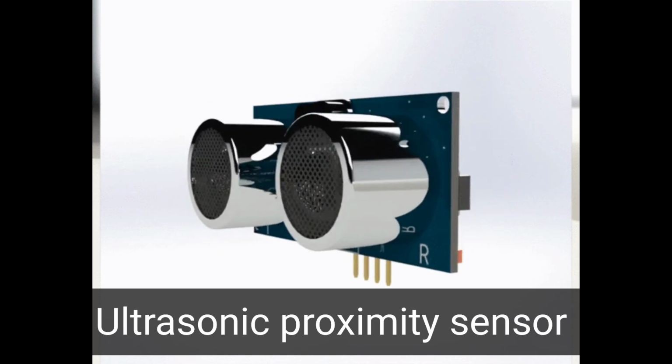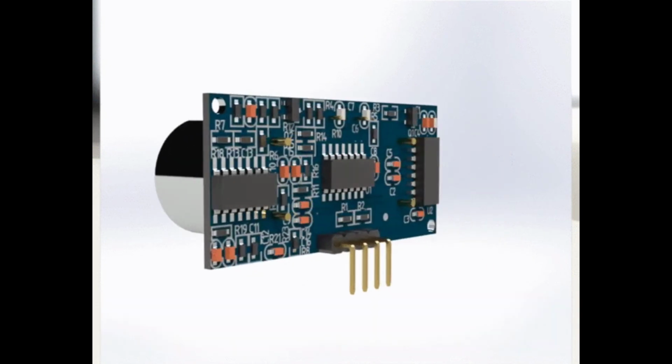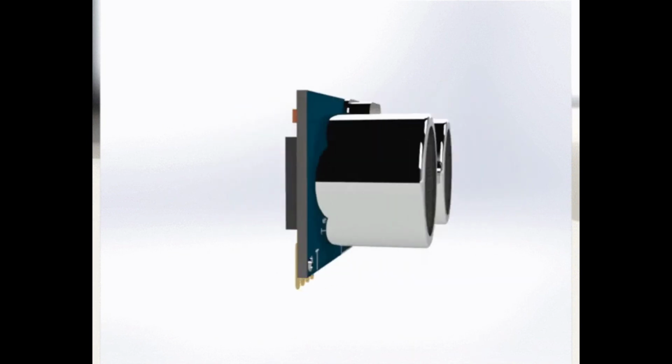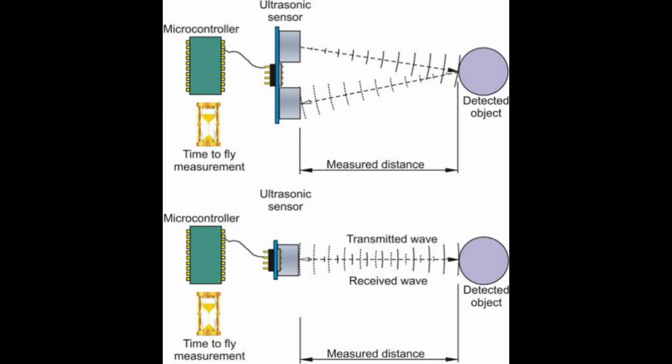Ultrasonic sensors use sound instead of light. The frequency range of this sensor is higher than that of audible sound for humans, approximately greater than 20 kHz. The basic principle of this sensor is to transmit an ultrasonic signal and get a signal back. By using the time difference between the transmitted and reflected signal, the distance to the target can be determined.